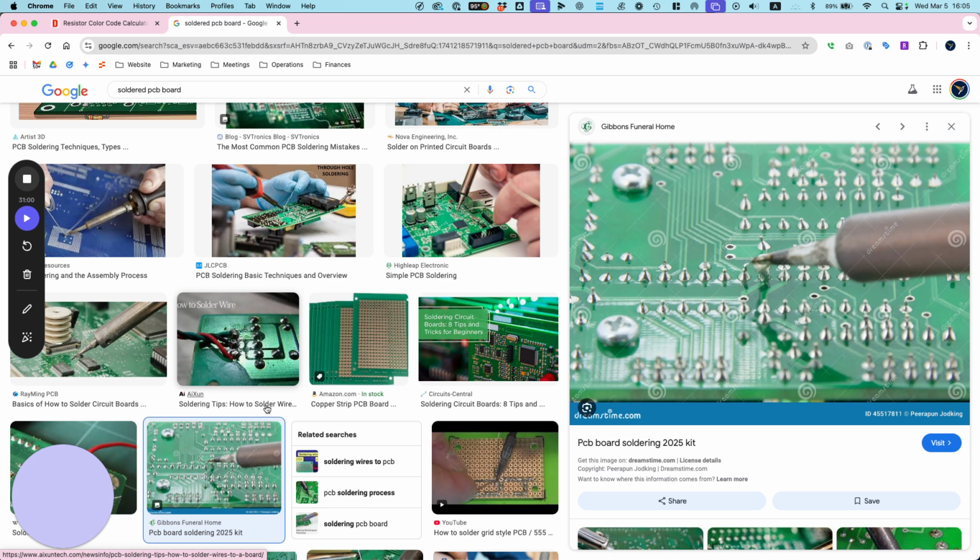Now, if you look here, I actually didn't do a great job soldering this LED because look, it's not flush. So I'm going to fix that. It's this side that didn't do well. So I'm just going to supply pressure on the back while I reflow that. So I'm going to heat it up.